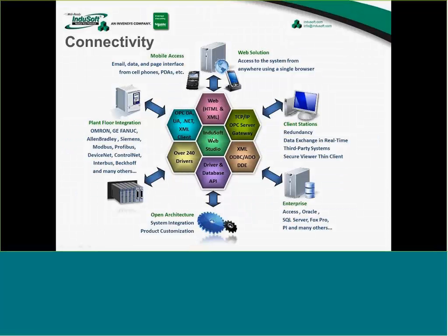So this diagram, if we take a look and we think of InduSoft Web Studio at the core of this, or more importantly, our tags database at the core of this, and most of the time, what many of you are going to do is use one of our over 240 drivers to communicate with just about any PLC that you can imagine, or PLC network, and bring data into the tag database and then show it on the screen, and maybe show a trend or a bar graph or a set point or an alarm, things of that nature. That's a very common way to do this.